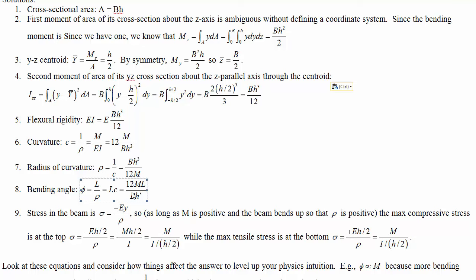The biggest effect on bending, though, is the thickness. Thickness affects the rigidity of the beam according to thickness cubed. So as things get a lot thinner, they become much, much easier to bend. This is probably the number one reason that paper is so easy to bend: it's so thin.